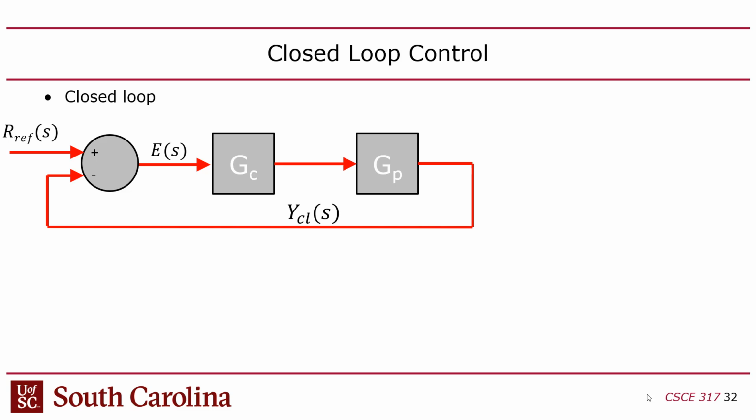I'm going to manipulate this variable in order to achieve the desired process variable state, and that's going to be determined by this ref, which is my set point. I'm going to use this subtractor here, so I take the reference, subtract the process variable from it, and use that as the input to my controller, which is usually called the error signal, or the controller input.